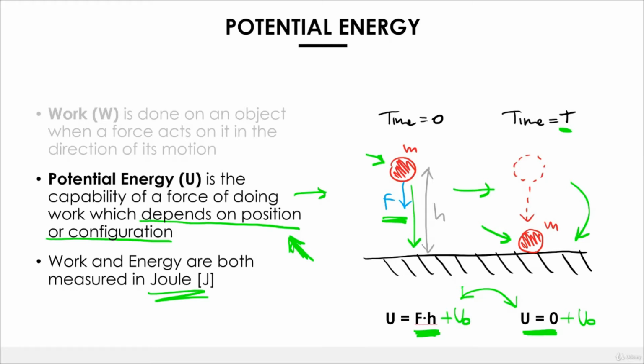This is something really important to understand, because potential energy is intimately related to voltage, and the same concept, exactly the same concept, also applies to the voltage. When you say that in a certain point there are 3 volts, in reality, all you're saying is that in that point, there are 3 volts more than some other point. It doesn't really mean that that point is absolutely 3 volts. It's simply the difference relative to another point of the circuit.